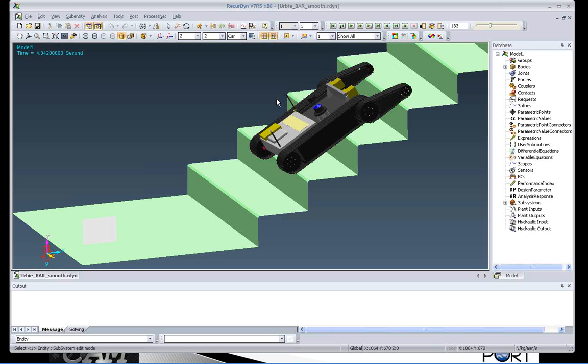So the best practice is to do a simulation like this, compare it to physical results once you have a physical prototype or an actual product to test, and get the physical results for the load data that you can obtain readily from the testing and from the instrumentation, and make sure that that's all matching. And if you have a model that's matching those measured loads, then for areas that are really hard to measure, you have good confidence to use the loads from the simulation.